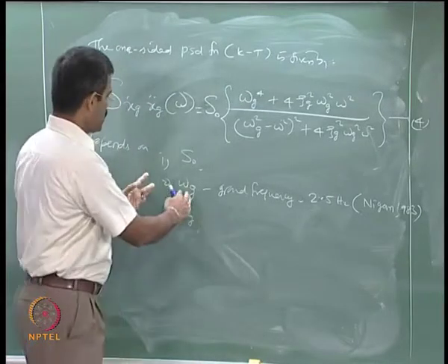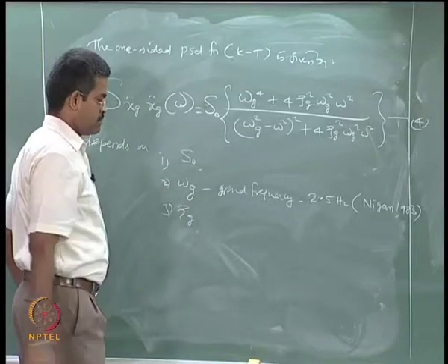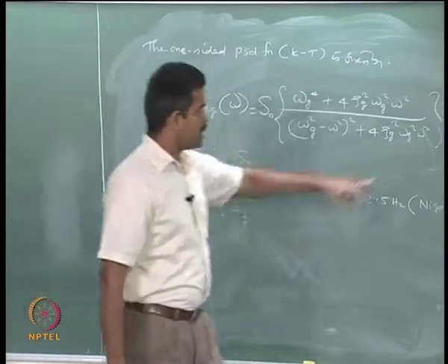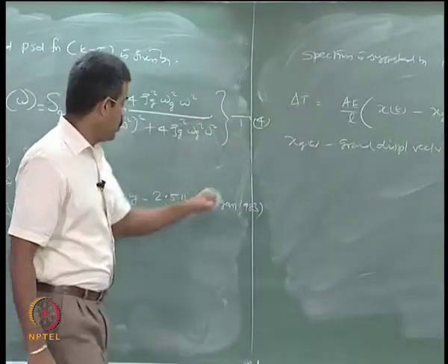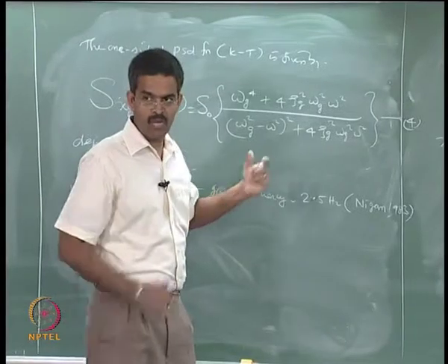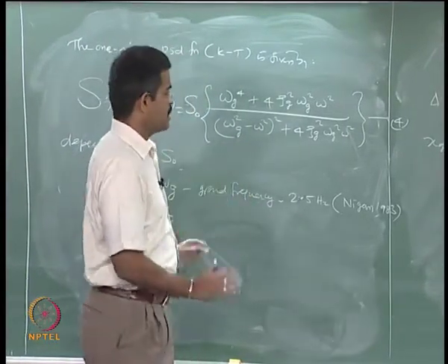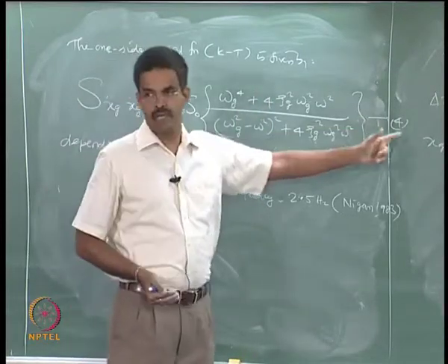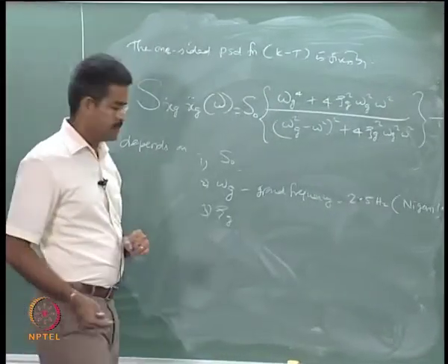Why are we using a stiff system in this literature? Because, as I explained in the previous discussion, delta T naught is directly superimposing the values of earthquake excitation on a stiff degree like heave. Therefore, it is as good as the structure resting on the seabed under this delta T naught. Therefore, we have used 2.5 hertz as the ground frequency.